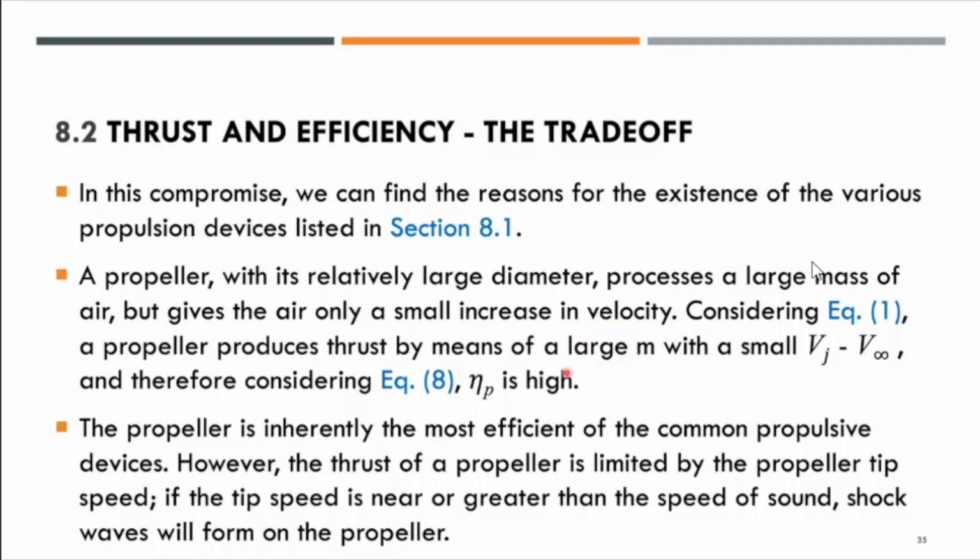You will get a high propulsive efficiency. However, the thrust of the propeller is limited by the propeller tip speed, because you cannot turn the propeller higher than the propeller tip speed. Otherwise, it will be damaged.